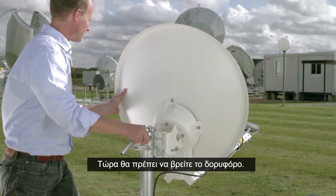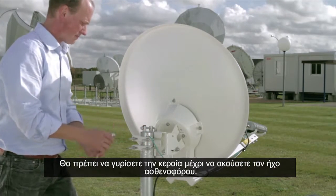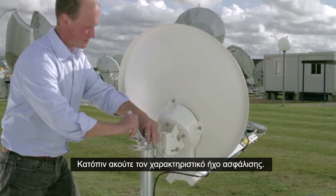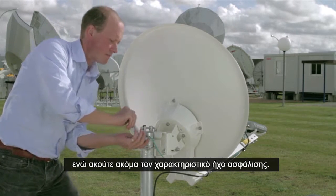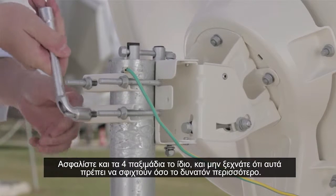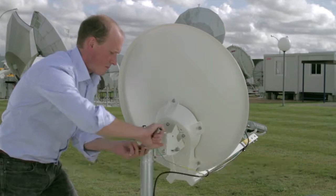Now we are going to find the satellite. You should turn the antenna until you hear the ambulance tone. You then hear the locking tone. Now, lock off the mast clamps while still hearing the locking tone. Lock off all 4 nuts equally, and remember, these should be locked off as tight as possible.